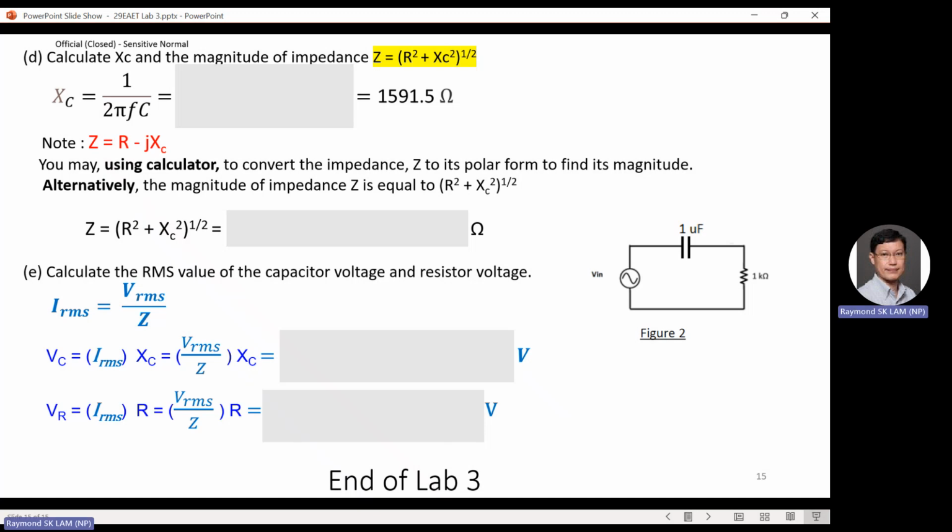Okay, you must understand the breadboard. The breadboard here, all these holes at this back part, do you see this one? All the holes are connected. Behind that, 1, 2, 3, 4, 5 are connected. So you connect like that. Or you connect here, and this one you connect here. Or you connect like that, then another wire connect like that. You have to understand that. Otherwise, you might have a problem.